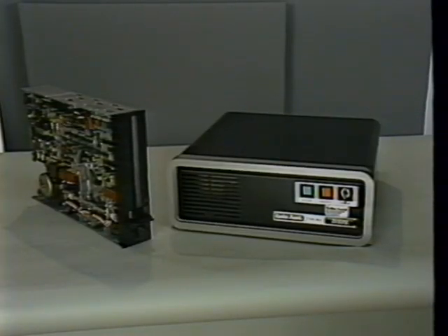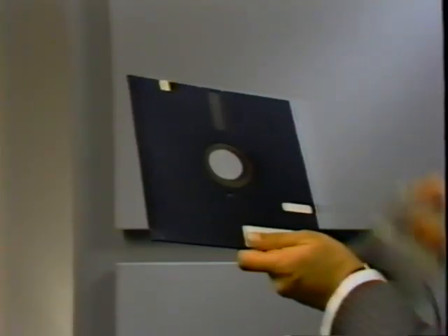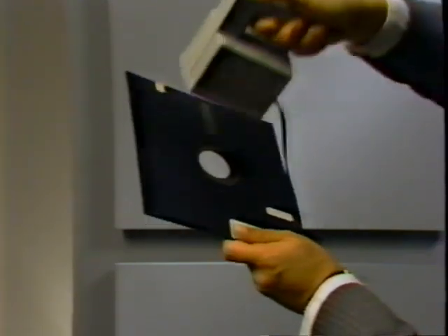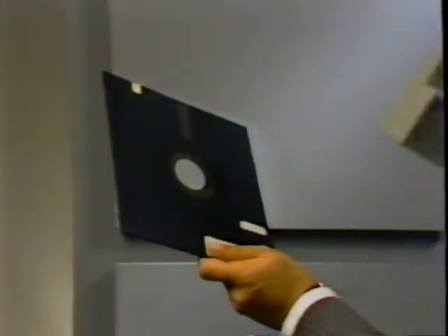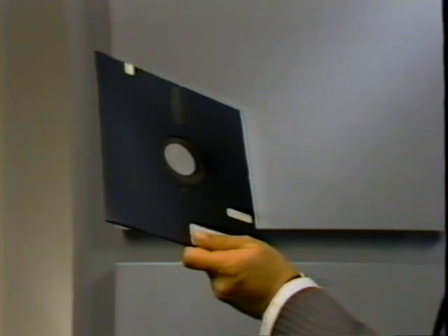The next class of diagnostics that we will discuss are media verification diagnostics. These check the storage capabilities of hard, floppy, and other types of drives. With these diagnostics, good, freshly formatted media are extremely important. When testing floppy drives, bulk erase and format the test diskette. For cartridge drive tests, format the test media, but do not bulk erase it. Bulk erasing a cartridge destroys irreplaceable factory-written information. Formatting does not affect this special data.